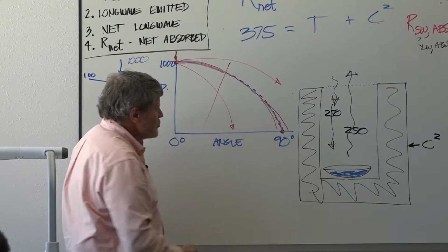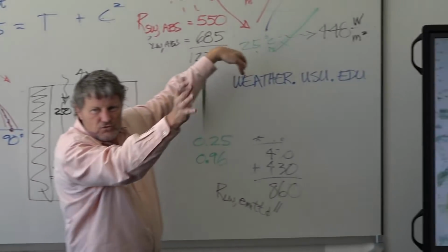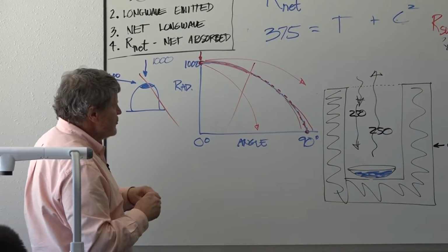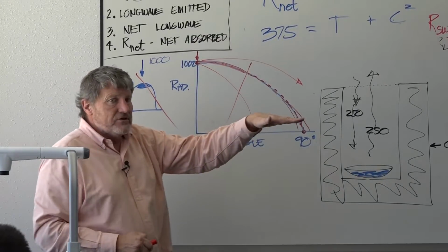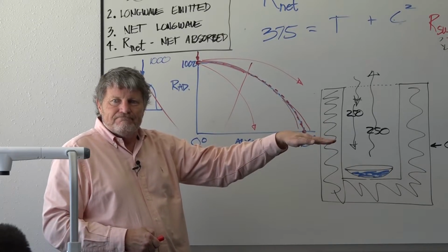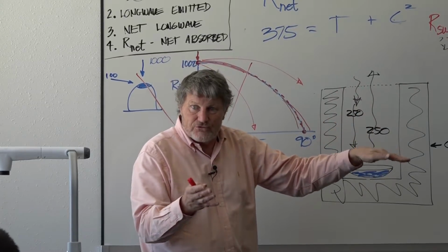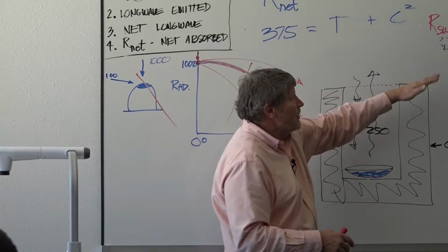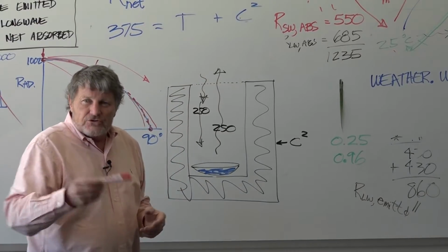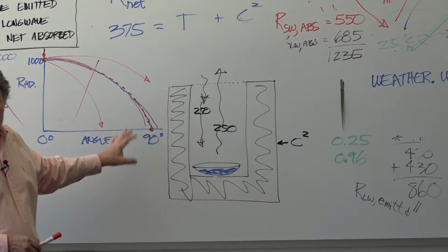So this is cosine correction, and I think this speaks to your example of angles in here and what happens when you tilt things. How does it change it? Our instruments measure, by definition, what the radiation would be on a flat surface. And if you want to calculate the radiation on a tilted surface, you can, with a little trigonometry, and like Mark just pointed out, if you tilt it, it goes above 1,000. But that's one way to explain the effect of tilted surfaces.